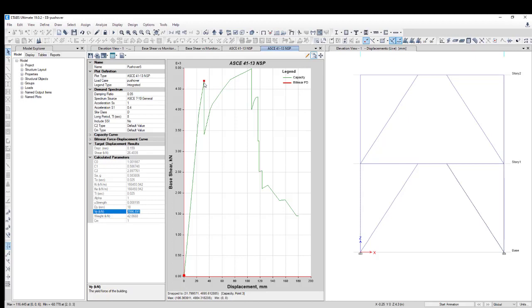The maximum is about 4600 or 4700 kilonewtons. But after the first part of the braces is damaged, the other remaining parts will go to the ultimate area, and it will get this maximum resisting force with a maximum of 105.6 millimeters displacement.